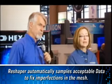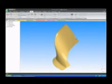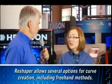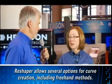Okay. So I have the mesh all cleaned up. My next step would be to place contour lines on the mesh. These lines would be projected directly onto the mesh. And the reason I want to do that is the contour lines are actually going to be the B-splines that I'm going to import into my CAD package. And where the B-splines intersect to form valid four-sided patches, that's where I'm going to get a surface that I can then pull into my CAD package.